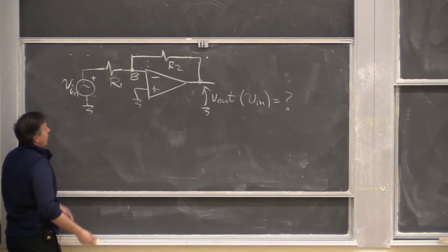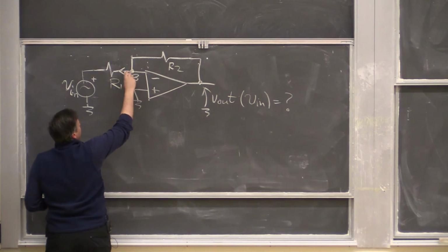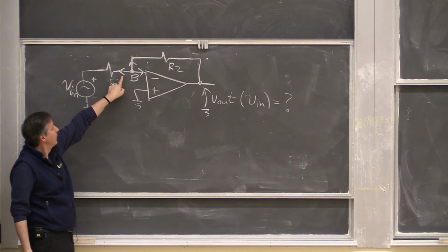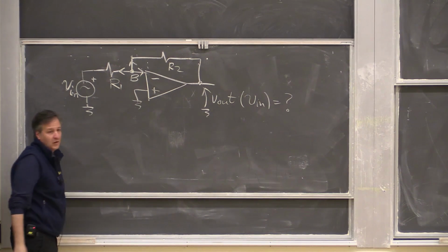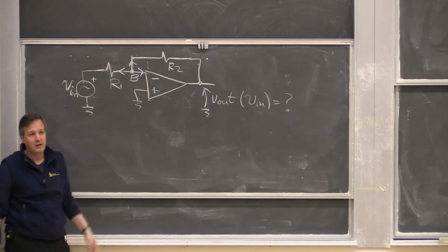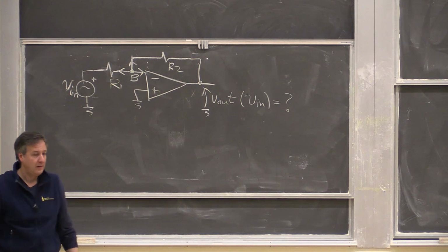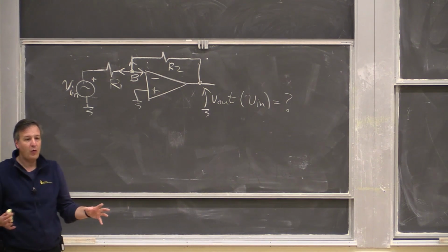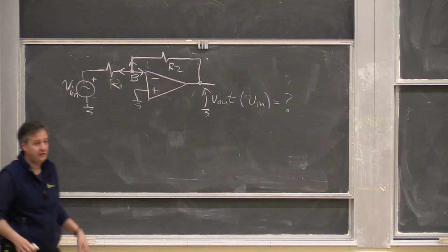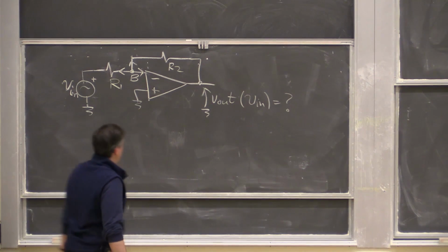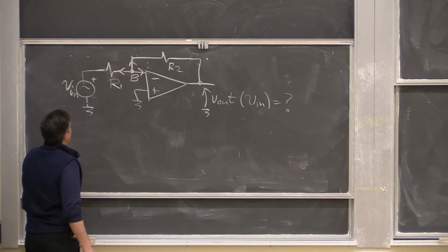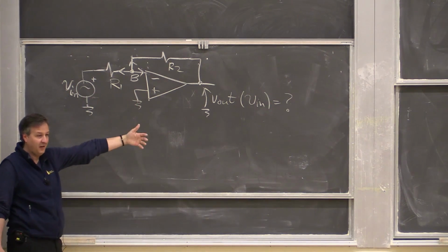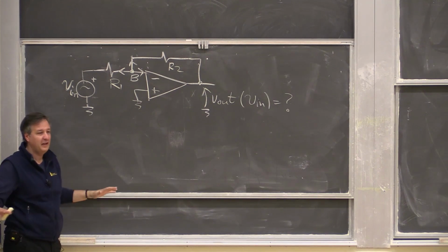And it's a single nodal equation you need to write. Okay, who can tell me what will be the terms? I'll just label the flows. There's 3 flows. Okay. So for this term, what do we have? For the left. Don't worry yet about knowing whether golden rules apply or not. You don't need any of that. Yes? For that one, it's negative V in over R1. Okay, so you're saying negative V in over R1. You jumped a few steps. So I just want to do very vanilla nodal.